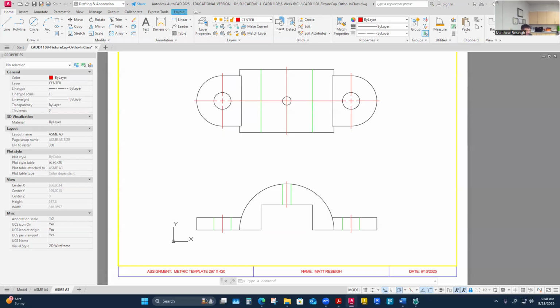The whole reason why I'm saying this, I can't remember. There was something about flexing. It was the term flex that made me think of it. Sometimes I have to flex my scale in order to get the text to auto update. Sometimes when your viewport is locked, it doesn't allow that flex to happen. So sometimes you just have to unlock it, flex it, and then lock it back up.